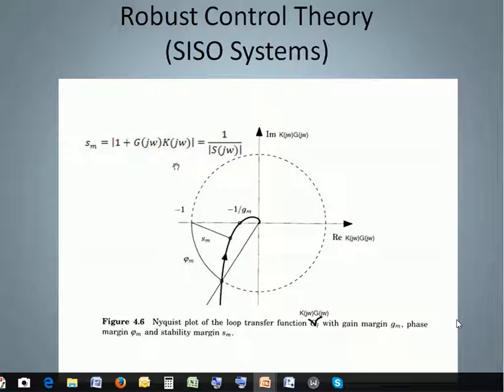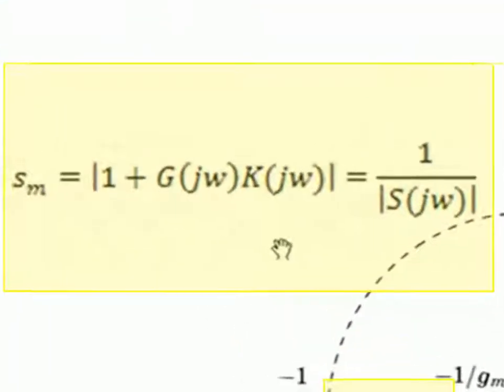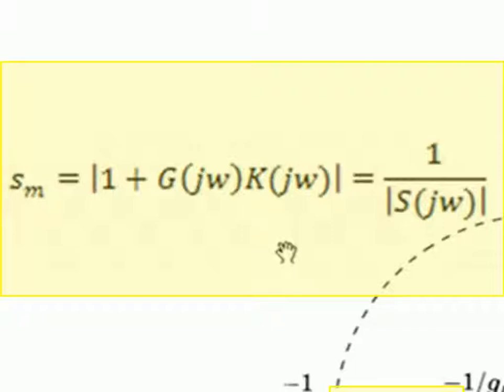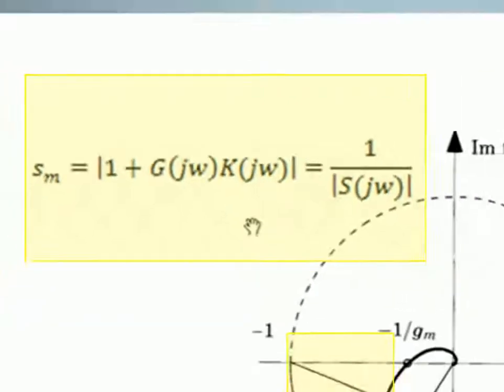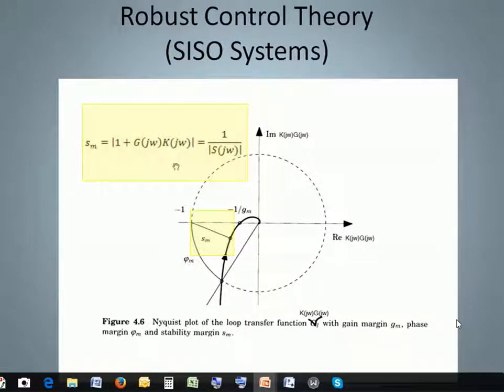And for that, we could add another stability margin. In the plot it is called SM, the inverse of the magnitude of the sensitivity, also called the magnitude of the return difference. Requirements for robust stability may then be: A, the Nyquist of the open loop transfer function must not go around the point -1 j0. This guarantees absolute stability. And B, the magnitude of the return difference cannot be smaller than a predetermined value. We can see an illustration of this in the next slide.